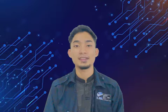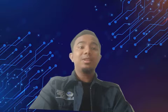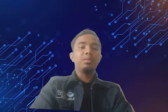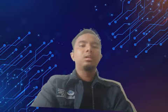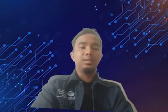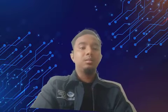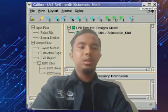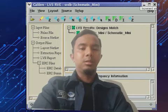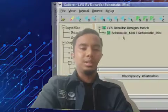That is LVS. Okay, Fakrul. Thank you, Munir, for your explanations. LVS is the last process of our mini project. It functions to compare the netlist of the schematic generated in DA and the netlist of the layout generated in IC Station. After completing the steps needed in Mentor Graphics, the LVS report will appear. Fortunately, we obtained no errors in our LVS check, and it was considered a success on our first attempt.